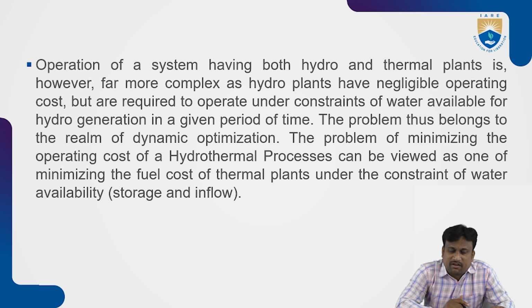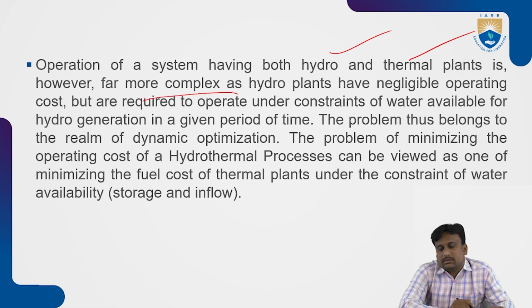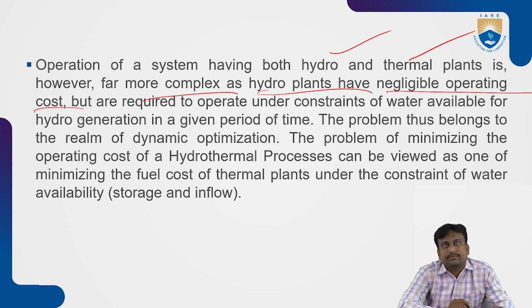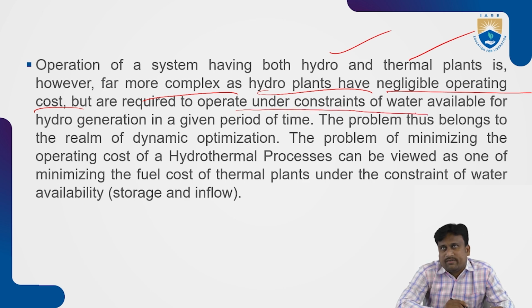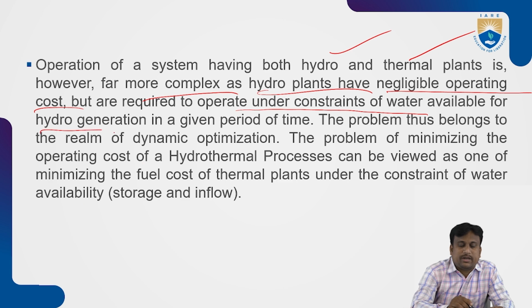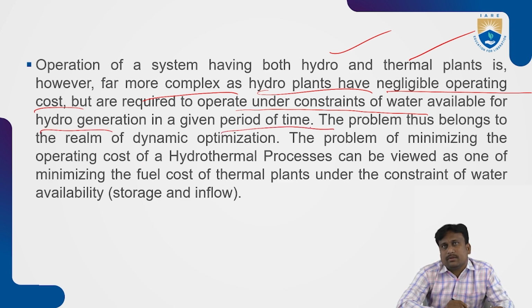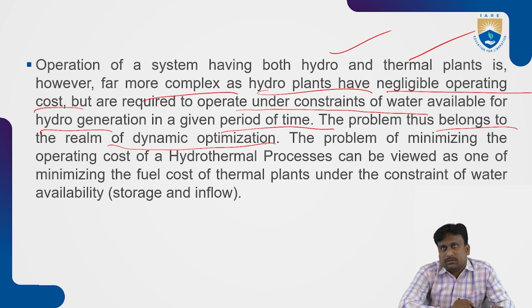The operation of any power system, whether hydro or thermal, is more complex. Why? Because hydro power plants have negligible operating costs, but they are required to operate under constraints of water availability for hydro generation, over a given period of time. So the problem belongs to real-time dynamic optimization procedures.